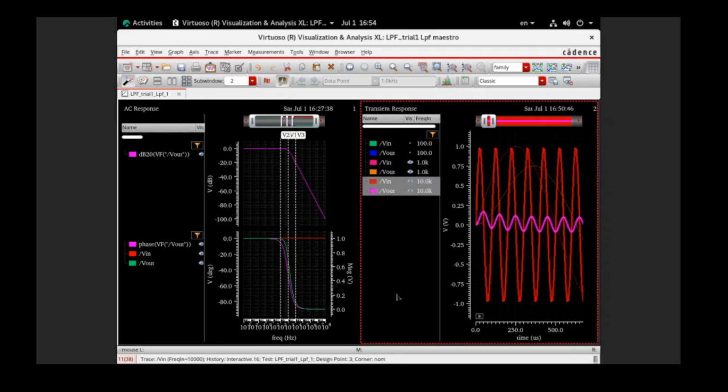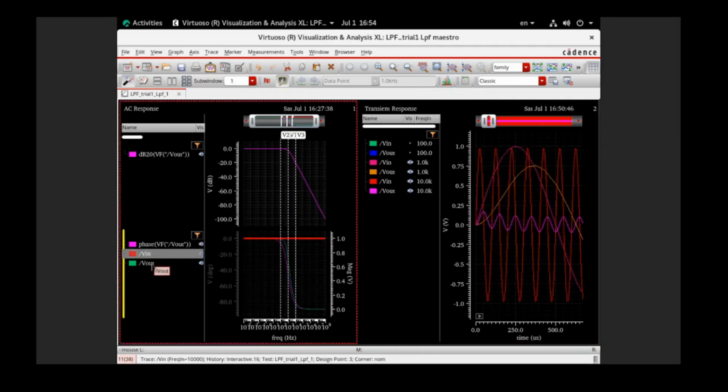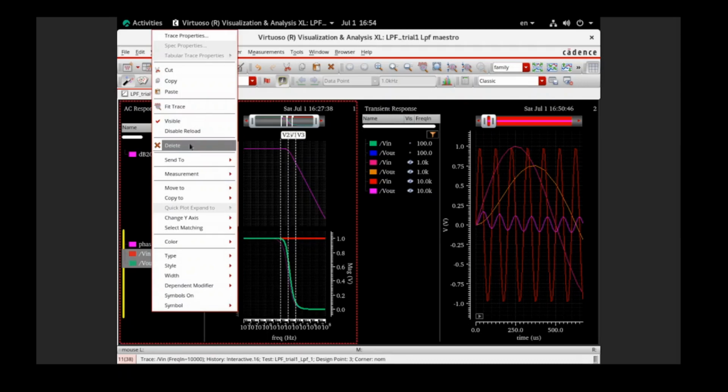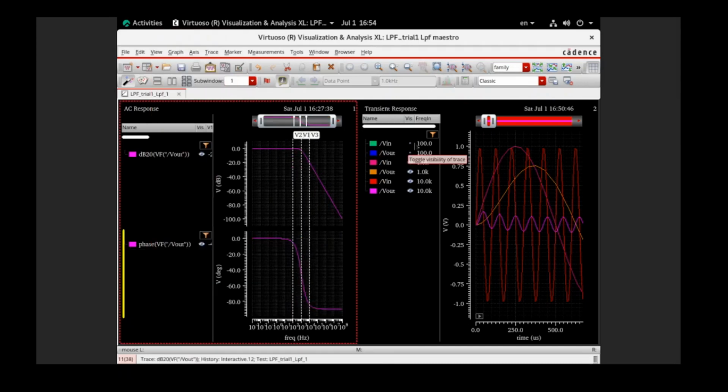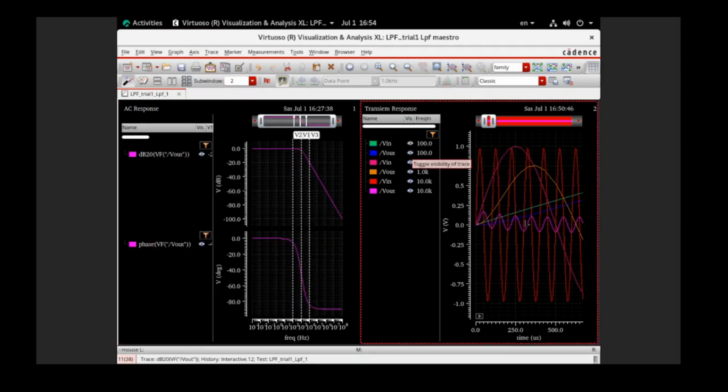And that's how the parametrization will help you. That's how parametrization is useful if you want to plot a lot of cases and compare between them very fast. You don't want to do one by one. You can do all of them in one simulation run.